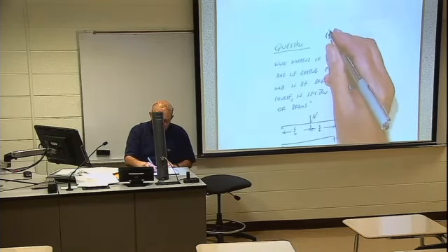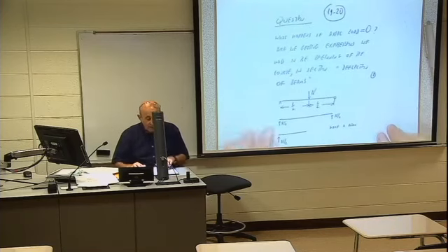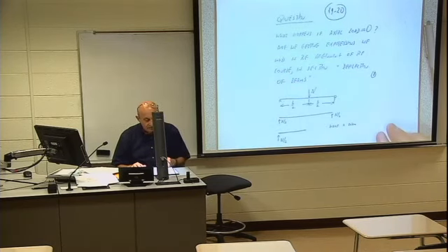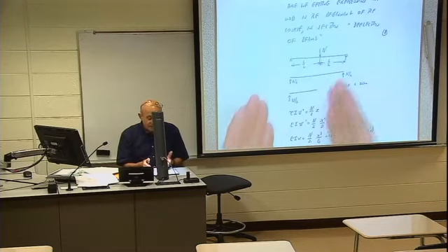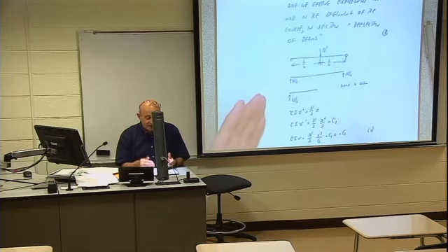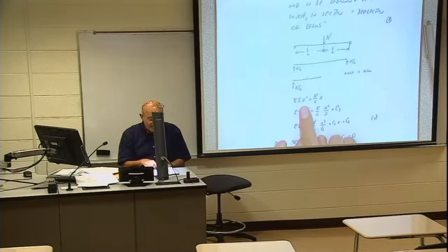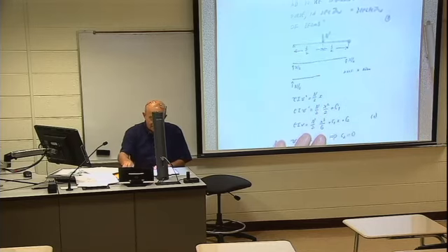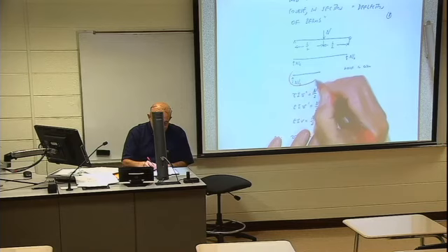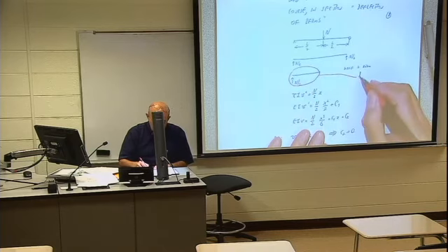So we will discuss one more question just. What happens if axial load is zero? Are we getting the expression we had in the beginning of the course, in the section deflection of beams, for this beam? Okay, for this beam, if you remember, that is how we solved. EI V double prime equals n over 2 times x for half a beam, because there is a symmetry, so we consider half a beam.